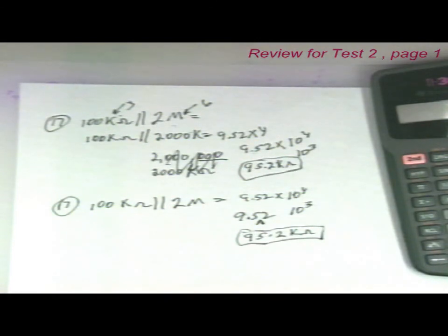Okay. If you had a two-branch parallel circuit containing R1 and R2, and you knew IT, how would you find the voltage? You know R, you know I. How would you find the voltage? Well, that's real simple, isn't it? E equals I times R, and conversely, I mean the same, V equals I times R, doesn't it? E and V are used interchangeably in a lot of places. Now, industry is trying to get away from the E, but again, it's in both of our lab manuals, so